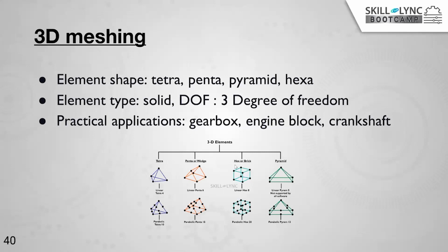This is the most commonly preferred element in the industry, if you're carrying out higher order, high quality meshing. This is the higher order hex. These are pyramid elements. This is most suggested for all analysis, or at least you can go with higher order TET if you're carrying out a structural analysis.